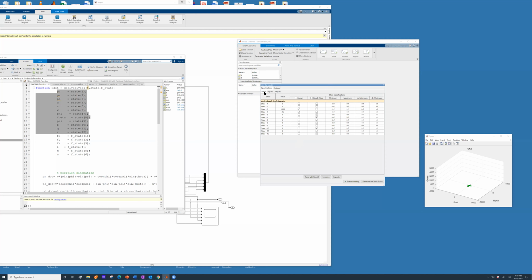So these are the states. And please understand, this is a numerical optimization technique. So we may have to go back and tweak some of these parameters to get a trim solution. But this is something we are going to start with. So airspeed 25, side slip 0, and I'm going to start trimming.